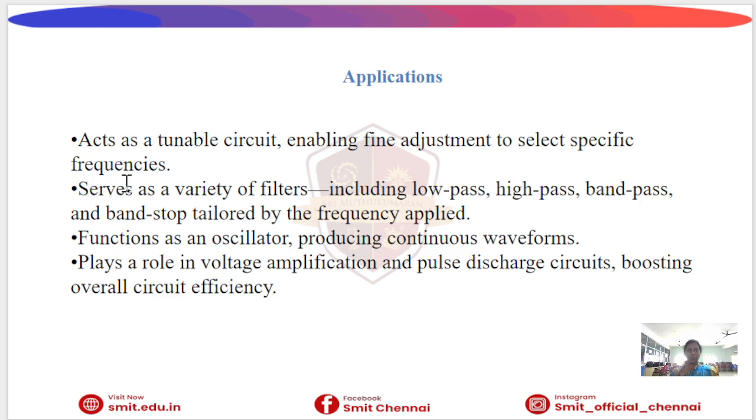Next one is the filters. They can act as filters such as low pass filter, high pass filter, band pass filter, and band stop filter. These are the filters we make using the parallel RLC circuit, and these filters allow a certain frequency and block the others.